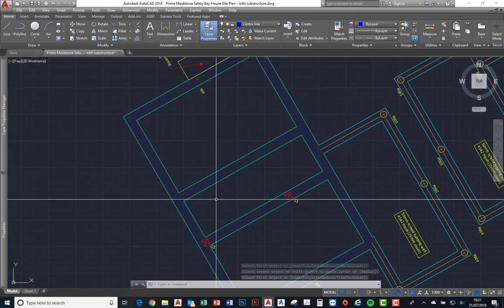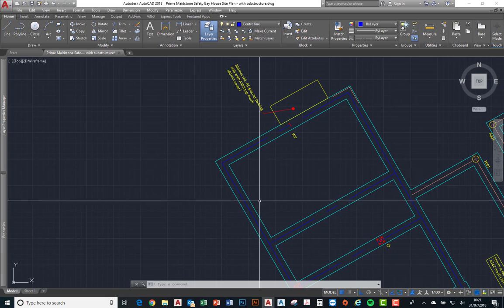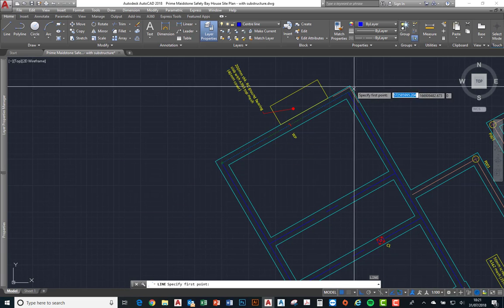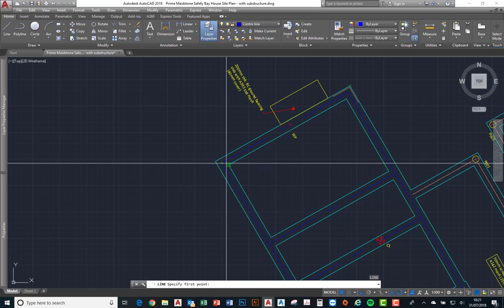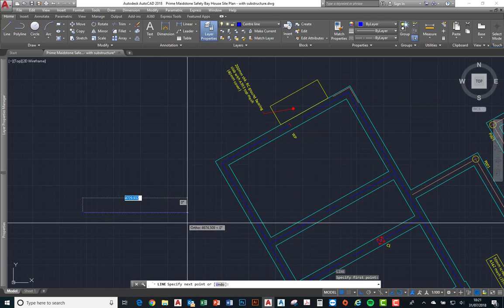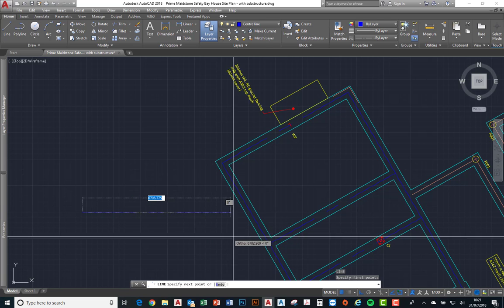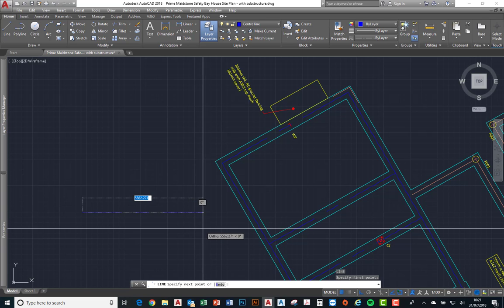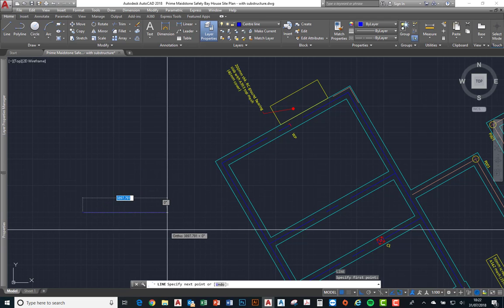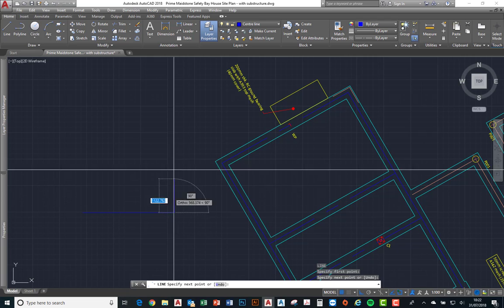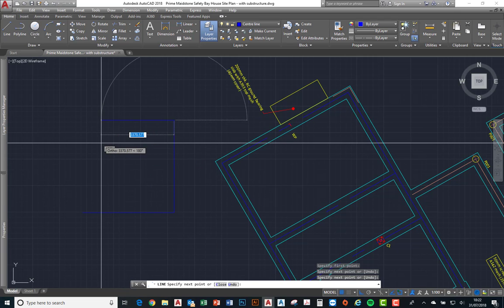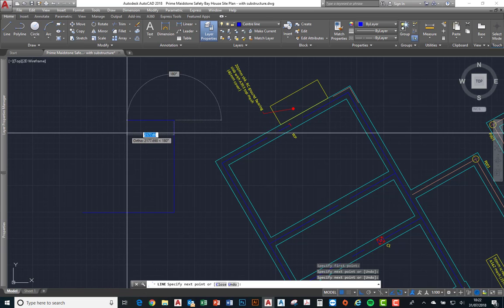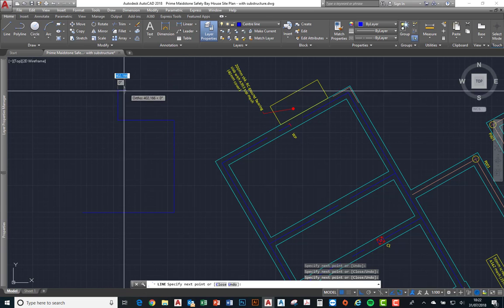The offset command is quite useful because if you imagine drawing a line, you would have to find out what the actual angle of this line is, and you'd either have to draw it at that angle, so you'd have to create an angle line to draw, or you could copy the existing line and move it down. But normally when you draw a line, you've got ortho, which allows you to draw vertically or horizontally on.